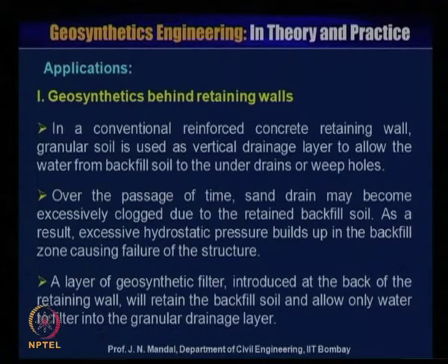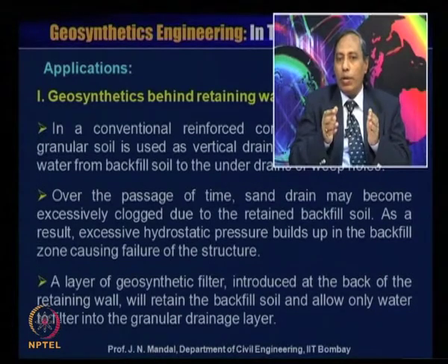Now, some applications of geosynthetics behind the retaining wall. In a conventional reinforced concrete retaining wall, granular soil is used as a vertical drainage layer to allow the water from the backfill soil to reach the under drain or weep hole. Over the passage of time, the sand drain may become excessively clogged due to the retained backfill soil.